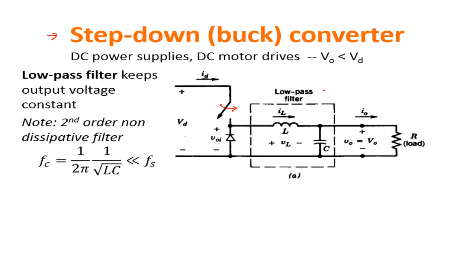You can see that it is a low pass because for the DC current, in DC the inductor is a short circuit, the capacitor is an open circuit, so this node has the same voltage as this one in DC. For high frequency, on the other hand, the inductor is an open circuit and the capacitor is a short circuit, so the output becomes 0.